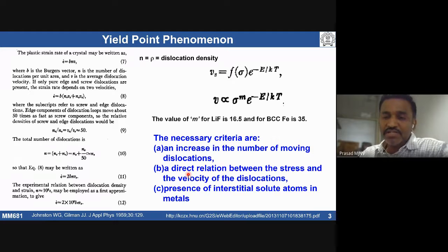The constant deformation is related to Luders band movement. Luders bands get initiated at the stress concentrated region, especially near the fillet radius, the radius of curvature you are seeing in the specimen. Those bands can propagate in one direction. The initiation and propagation of these Luders bands can sometimes be complex phenomena. As a result, we do see slight serrations in the lower yield point stress.